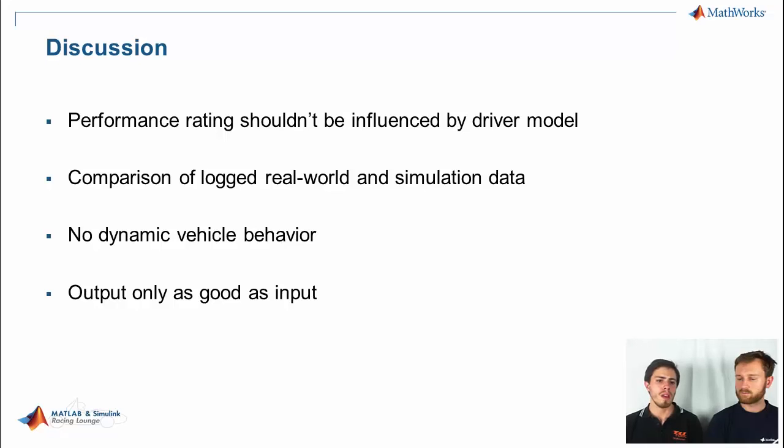Yeah, exactly. And we don't take into account the dynamic behavior of the car. That's a drawback of the steady state simulation. So, for example, the forces and the dampers, we cannot take them into account, but we can see from the comparison between the log data and the simulation that we don't really need it. Well, and I can imagine if you consider dynamic behavior, it would be a lot more effort in terms of CPU time, but also in terms of development effort. You have to get so much more input data.